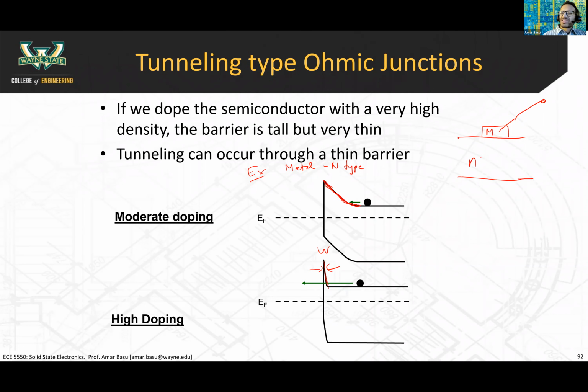Okay, so that's not always ideal because engineers like simpler systems, where it doesn't matter what metal I choose, it'll still work as an ohmic junction. I won't get this weird Schottky barrier effect. I'll get an ohmic junction every time. That's what we'd like to have. But if you just choose a metal and a regular doped semiconductor, that may not happen.